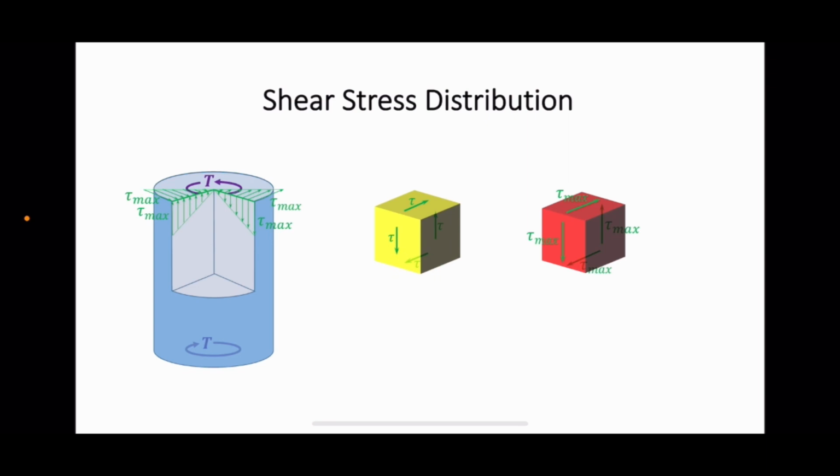Then, given the condition that the sum of the moments caused by the shear forces on differential areas of the cross-section about the center of the cross-section should be equal to the internal torque, we were able to develop an equation for determining the maximum stress. Finally, we concluded the lecture by visualizing the distribution of shear stress on both the cross-section and axial plane.